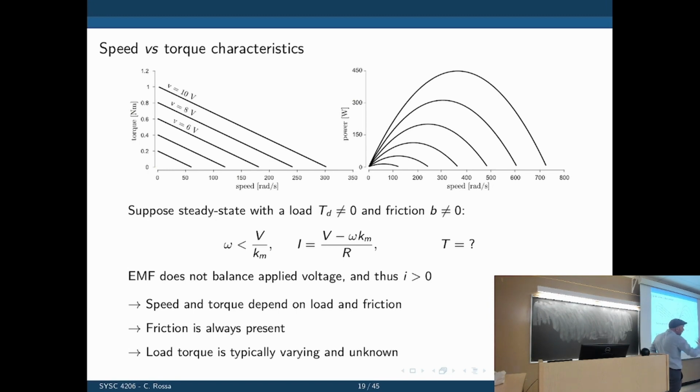It's the current, there is going to be some current there. That current is there to create a torque that is exactly the same amount as the frictional torque we get as the motor spins. If we apply a load to this, if I'm holding it now, what happens to the current? Does it increase or decrease if I slow it down by hand? It increases. Why would it increase?